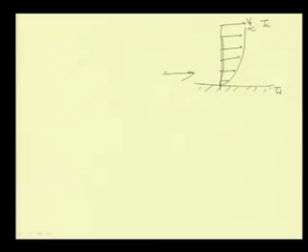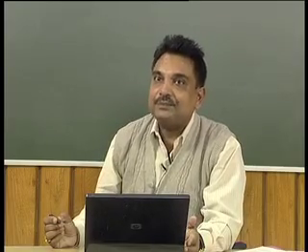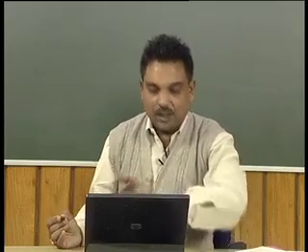That means between two successive layers, there is no more change in the velocity or the temperature of the fluid streams. These are called the free stream temperature and free stream velocity. That means the stream is free from the effect of the wall.